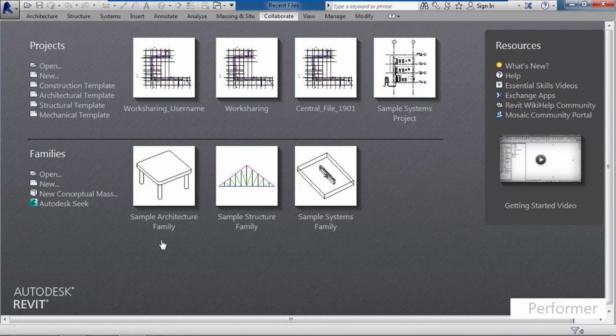What you really want to do is make a copy of either your file or the central file, and then detach all of the synchronization settings or work set settings that would tie it back to your central file. Now you could do this with either your copy, meaning your local copy, or the central file copy. Depending upon what you want to send to the consultant, make sure everybody synchronizes first. In this example, we'll use the actual file we have as a user.